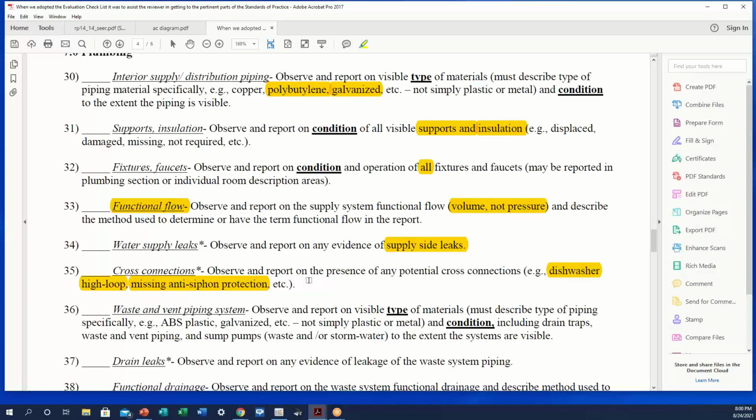Now, all the ones with an arrow aren't correct. So what we've been doing is we put our pressure valve on the one we want to check, and then we open the water, and when we open it up all the way, in the stem, there's 2 holes and water squirts out of that, the anti-siphon. That's how it functions. So we're able to actually look if it's not there. We should do a class on that one too. But these are Arrow brand faucets.